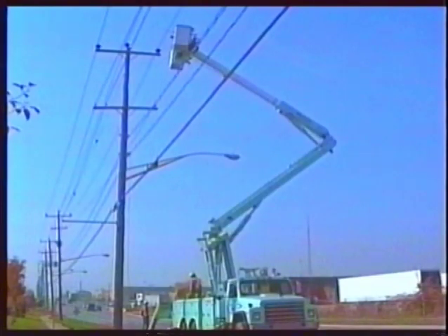There is one final group of protective devices that are found on large insulated bucket trucks. On trucks with boom extensions over 40 feet, the hydraulic fluid has a tendency to drain from the boom back to the reservoir, causing a partial vacuum in the upper sections of the hydraulic hoses. If a vacuum forms in the insulated part of a hose, it reduces the boom's dielectric strength, resulting in an unsafe condition.